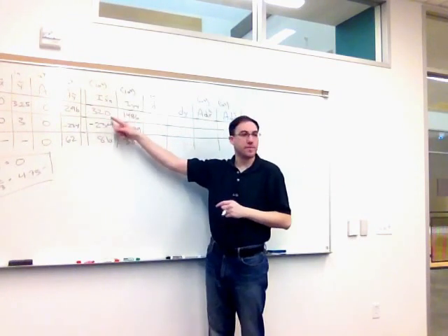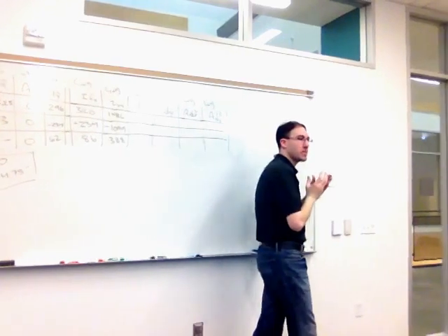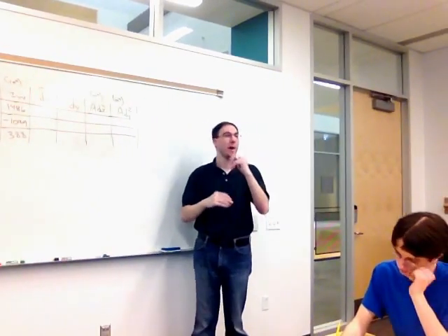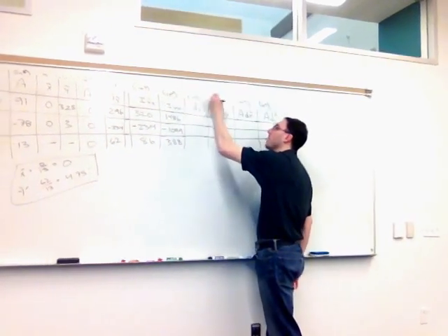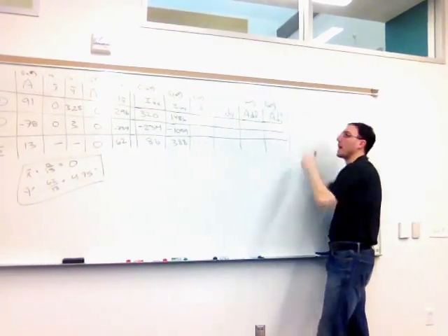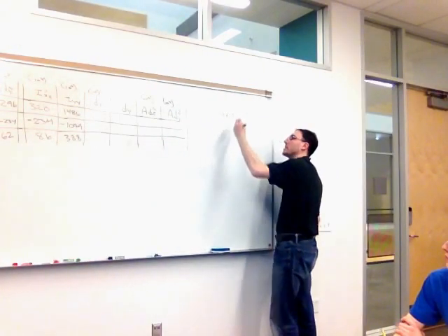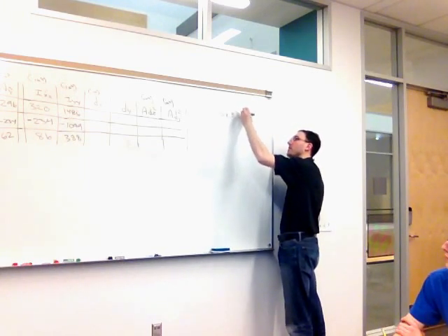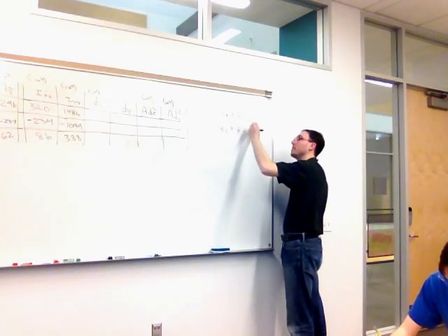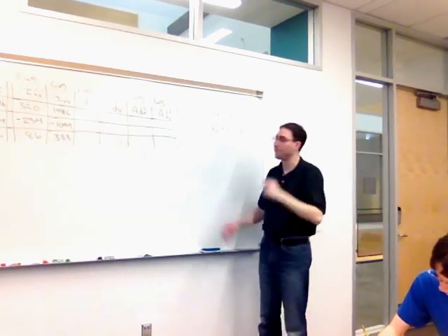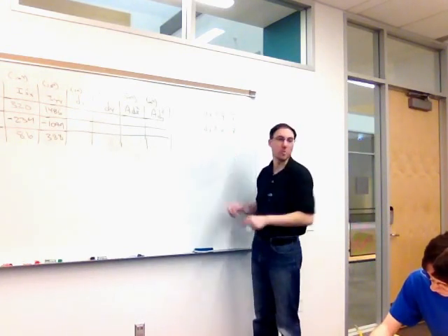These are only the moment of inertia about each shape's own centroidal axis. The goal is to find the moment of inertia of the composite shape about its centroidal axis. So I use these adjustment terms here, these dx and dy, which I then feed into Adx squared, Ady squared. This is where you have to, again, keep track of how I'm defining these things. Dx I'm defining as y tilde minus y bar, and dy I'm defining as x tilde minus x bar. So this is the confusing point, I think, of there's y's here, but it's a dx. There's x's here, but it's a dy.